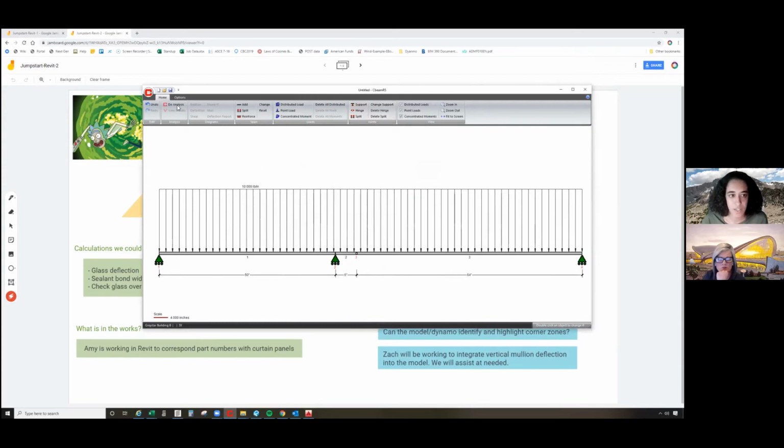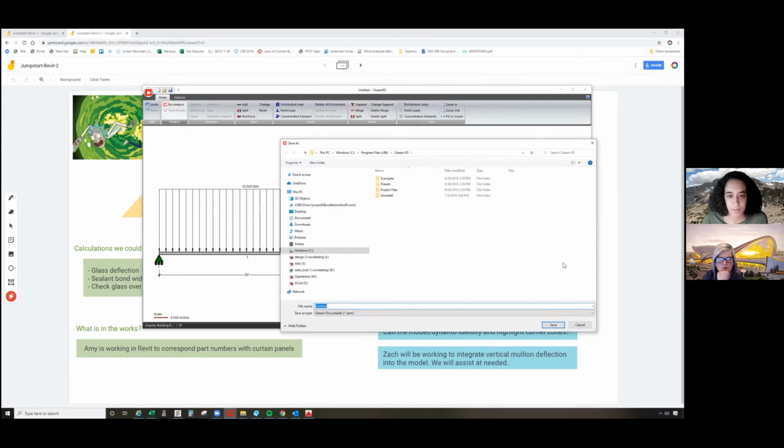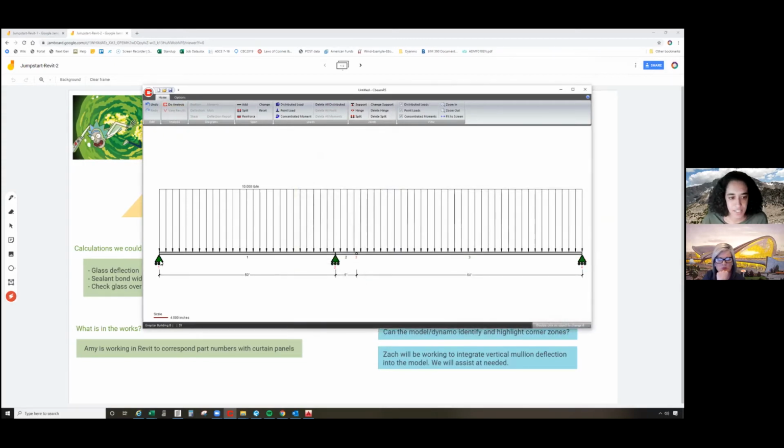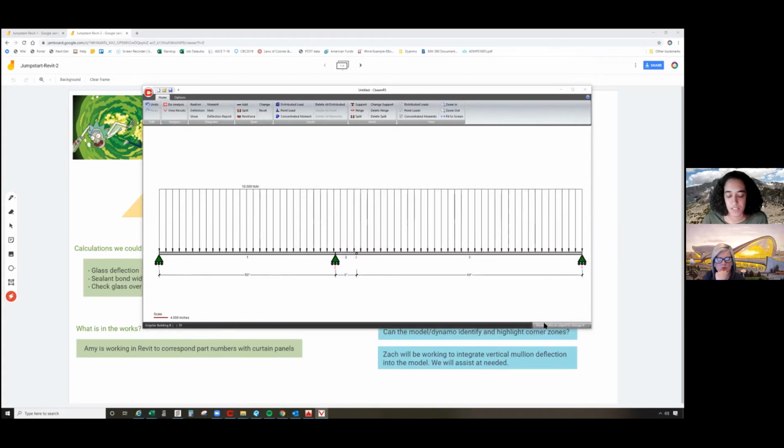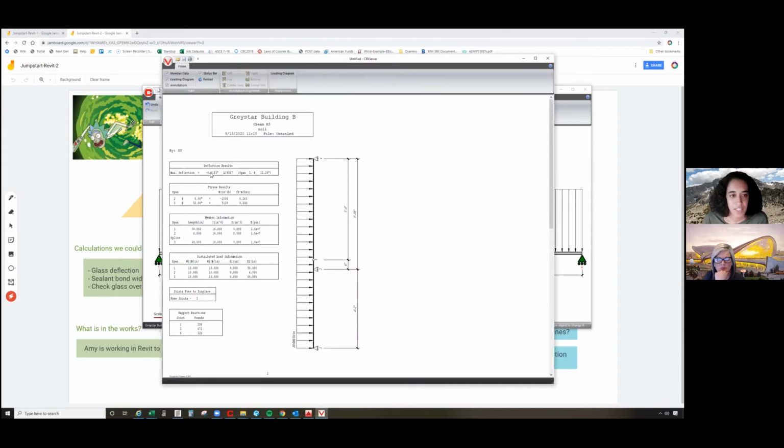And then we analyze the mullion. So let's say this is a sill. Here's the anchor. Here's where my chicken head is, separating the unit. Got 2 units. Here's the head. And then I'll do the analysis. Here's the analysis. It tells me my maximum deflection.